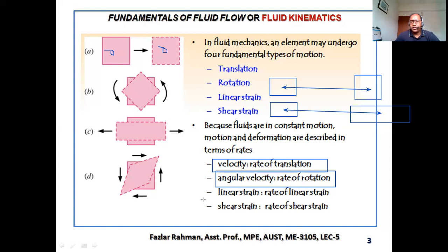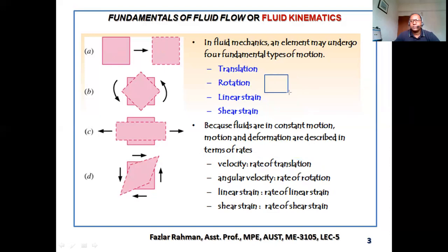Similarly, a fluid element remains at this point at time t. At time t plus delta t, that means within a millisecond or 1 second, this fluid element is coming right over here, and its shape is changing. So in that case, how will we figure it out? You figure out how much time it takes for the angular deformation of this fluid, not rotation.